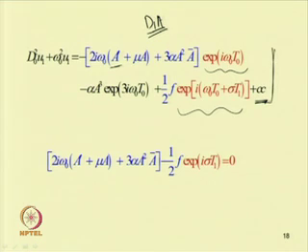Now, one can see that the terms containing the coefficient of e to the power i omega 0 t 0 should be eliminated, as this is a secular term, because the presence of these terms leads to an infinite response of the system, whereas the actual response of the system is bounded.